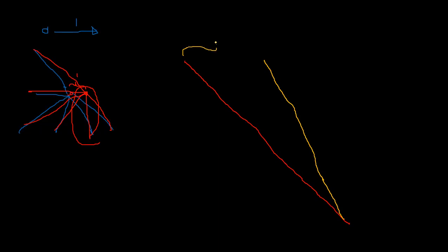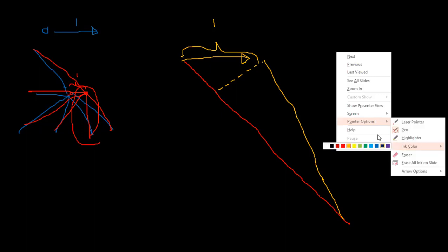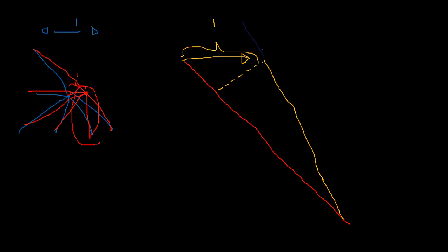So this is one unit displacement. So this has moved in this way. If you apply it this way, you can see the length is reduced. If the length is reduced, the applied force is what? A compression, right? So you can see the original length is reduced. So that means the applied force on this member is a compression.